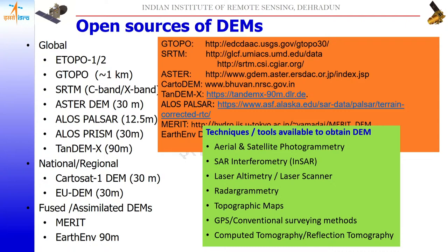Once you have 15 or 20 GCPs for, suppose, a 30 kilometer by 30 kilometer swath, then you can ortho-rectify, and after that georeferencing, you can improve the vertical accuracy and vertical resolution of this DEM, because spatial resolution is always good, but vertical resolution is not always good in open source DEMs. So if you are doing very sensitive work, fore and aft images are available from the Cartosat satellite, and you can use them to make your DEM with the help of GCPs.